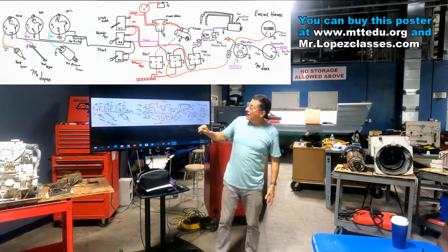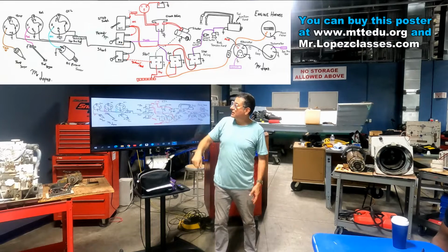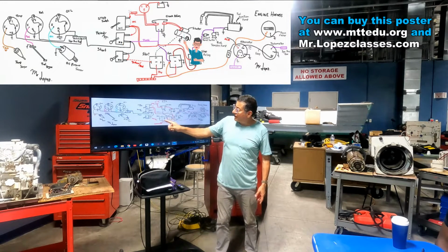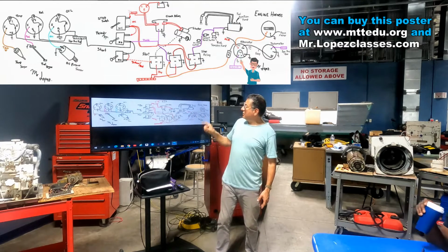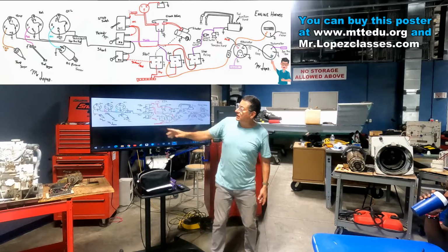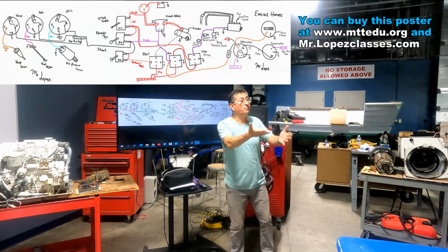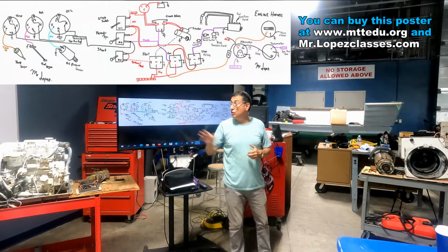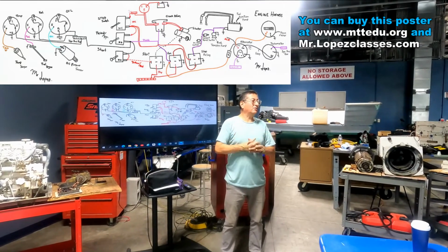We connect the ignition switch, stop, run or preheat and start, the crank relay, the start motor, the start relay, run relay, stop relay, the fuel injection pump, the alternator, the hour meter, the tachometer, the oil pressure gauge, the fuel pressure gauge, the temperature. That was your project. You remember in the previous class in DC current. You create this wiring, and this is the harness of the engine.